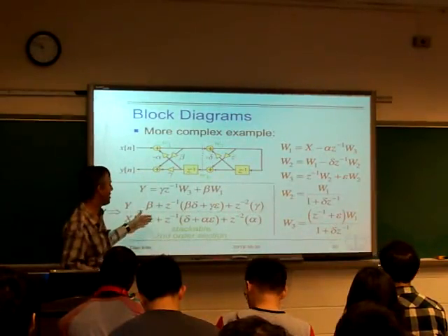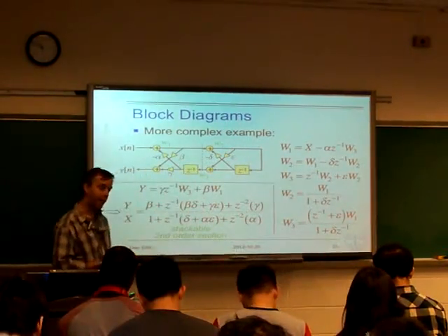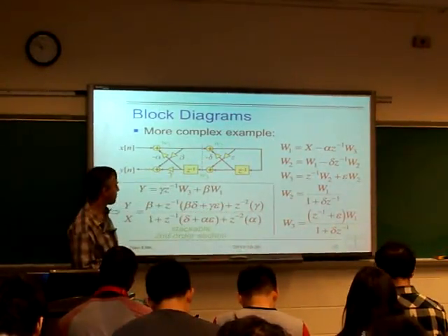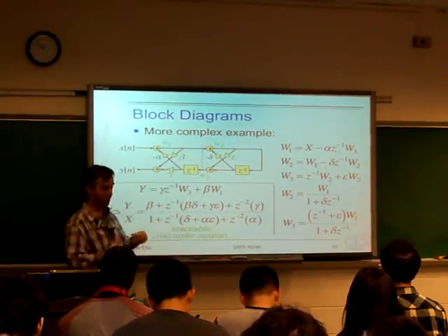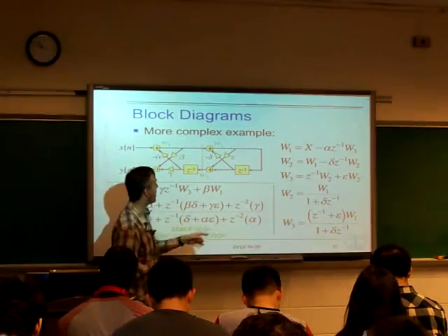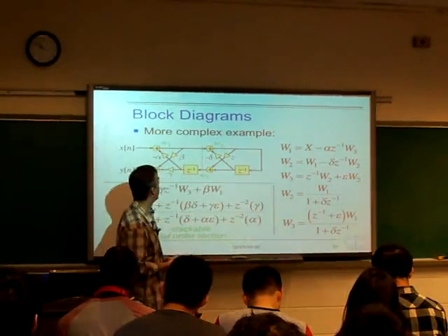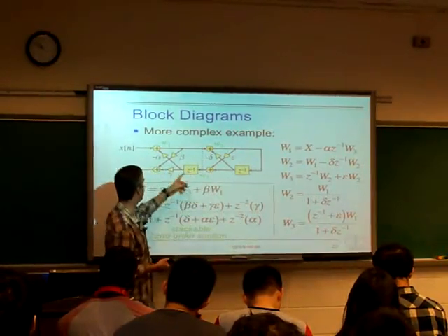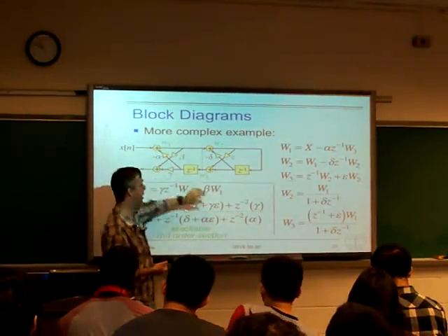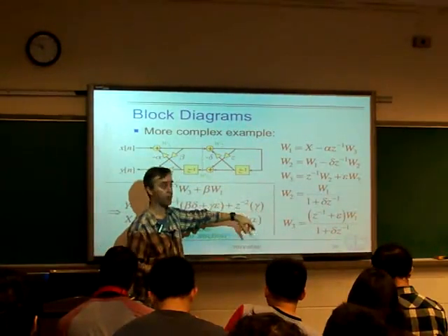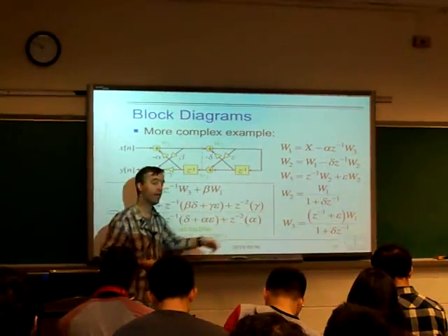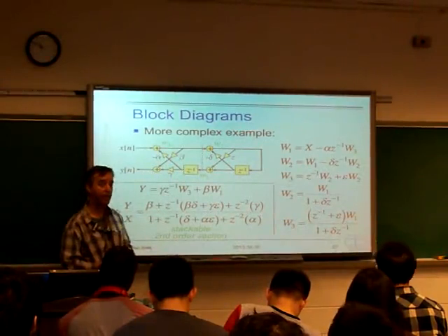And what it comes down to is that these are just simple second-order polynomials. So it's 2 poles and 2 zeros. By controlling these parameters, we can get an arbitrary set of parameters here. So we get arbitrary poles and zeros. But the nice thing here is that these things, which are r squared, are directly observable parameters here, gamma and alpha. And as long as we make these things smaller than 1, then r squared is going to be smaller than 1, which means that the radius will be inside the unit circle, so in particular, we can control the radius of the poles just by making sure that alpha is smaller than 1.